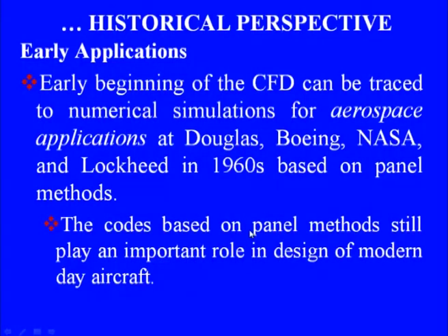And you will be surprised to learn that the codes based on panel methods and their improvements, which were developed in the late 50s and 1960s, still play an important role in the design of modern day aircraft, whether it is a fighter aircraft, a passenger aircraft, or a freight liner. So the first design we would use for a quick analysis, we would use panel methods.